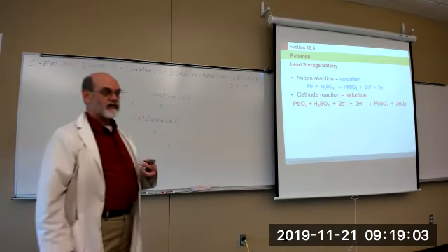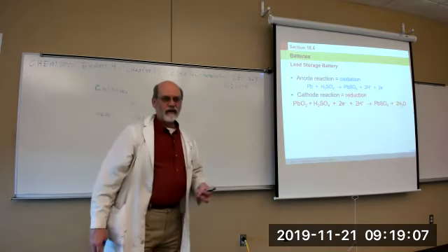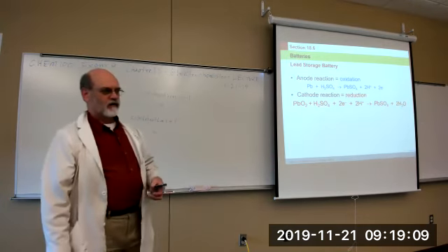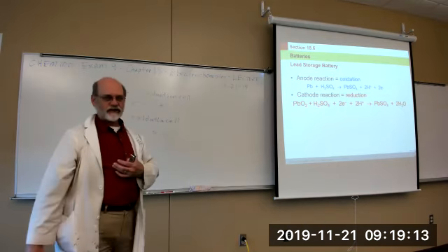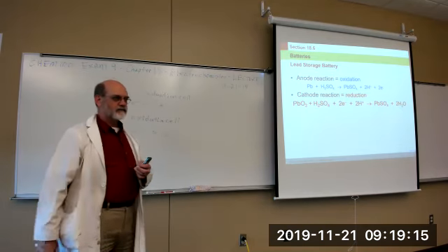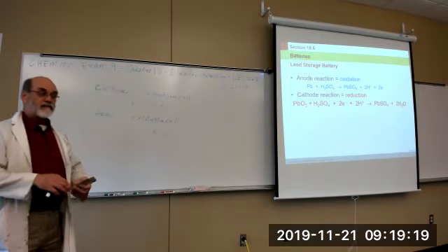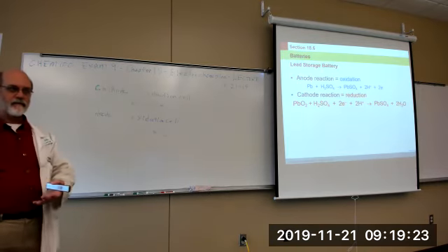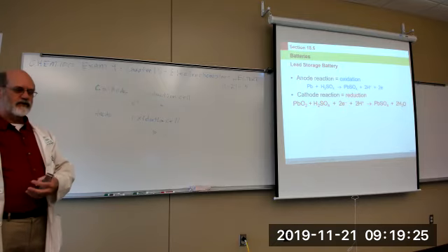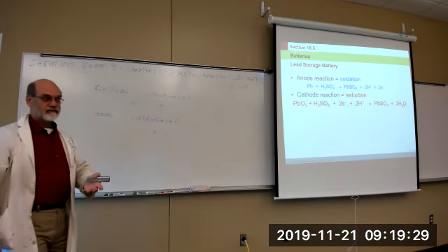And in the process, we're extracting that energy to run the radio in the car, or run that current through the starter motor, crank your engine over. And when you do that, you partially discharge the battery. You use some of its energy. So that the battery doesn't continuously discharge, we have an alternator hooked to the engine.